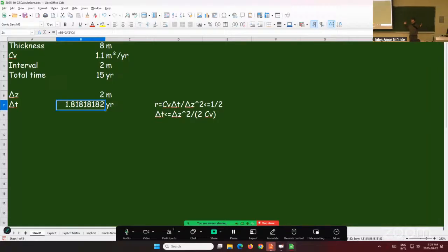Now, with the explicit method, if you don't do it, you will see what happens. It will not converge and it will be obvious. You will get some solution that makes a bit more sense with the implicit method, but the error may be large. So it's always a good guide to use this. Although the implicit will converge, remember that this is a good guide in terms of how big your time step can be, even when you're using another method. It's not a bad guideline.